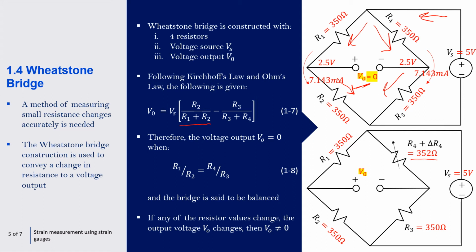And you'll notice here, if we work out, initially there's actually no change to the current values along the left half of the branch. The increased resistance, however, on the right half branch, so for R4, results in a drop in the current. So if you're looking here at the current, the value is actually decreased.